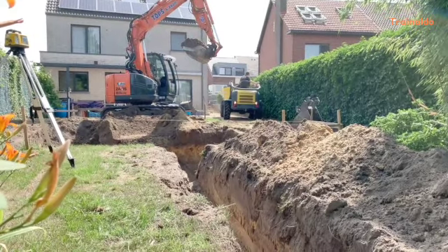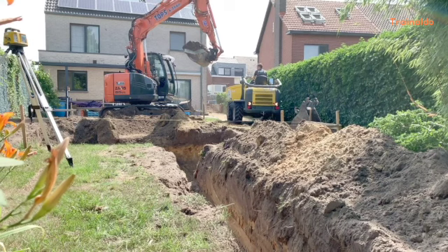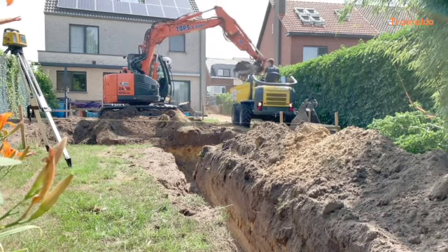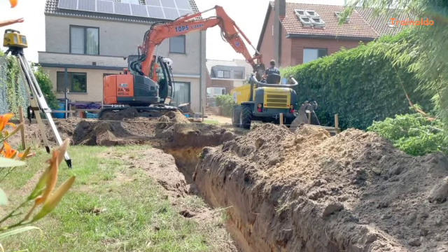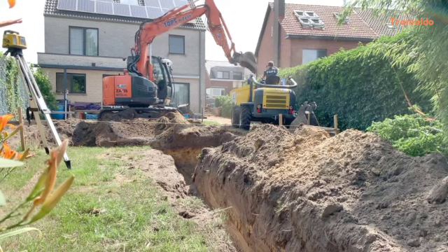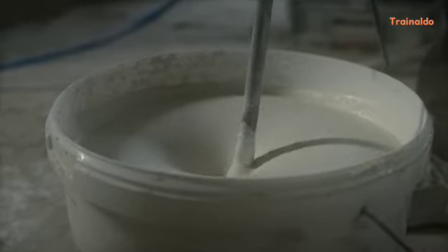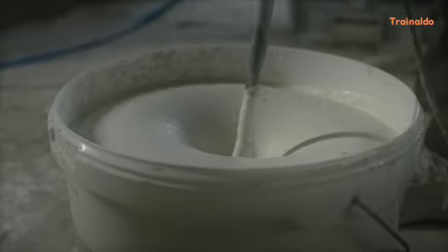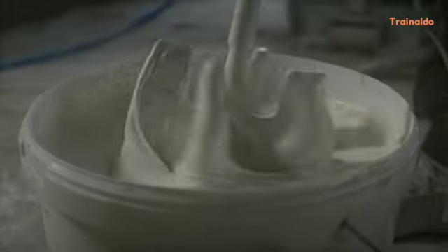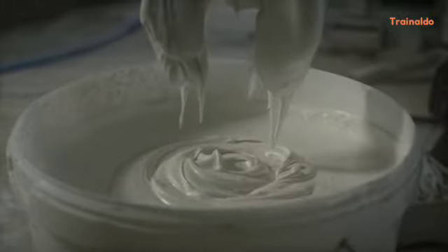For instance, if there's an unsafe trench on site, eliminate the hazard by backfilling the trench once the work is complete or installing barriers to restrict access during downtime. Substitution. If elimination isn't practical, substitute the hazard with something less risky. For example, if a chemical adhesive used for tiling is harmful, replace it with a water-based, non-toxic adhesive.